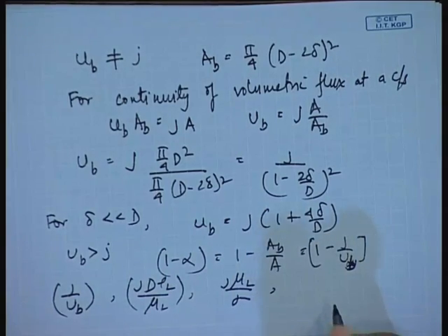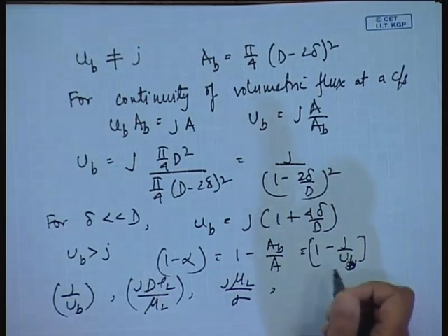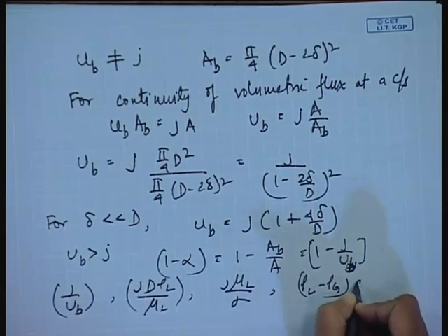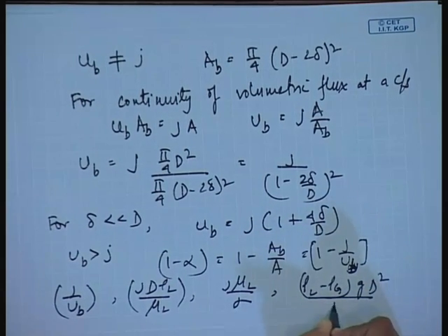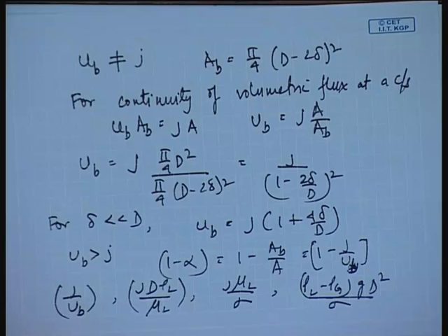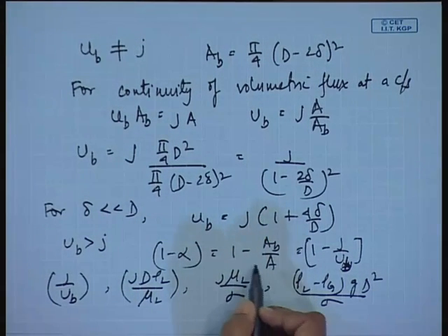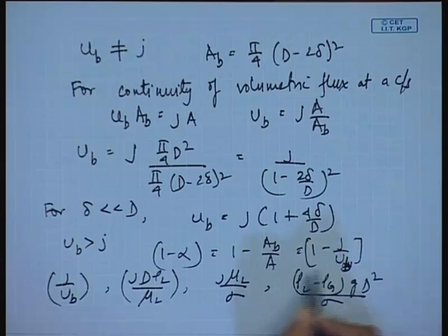When buoyancy becomes important and the entire gas goes up. So, in order to decide the limit of this slug flow pattern, buoyancy by surface tension also has to be important. Mostly we will find that these three terms will be governing, and the limit of slug flow will be governed by this particular term. Do you agree with me?